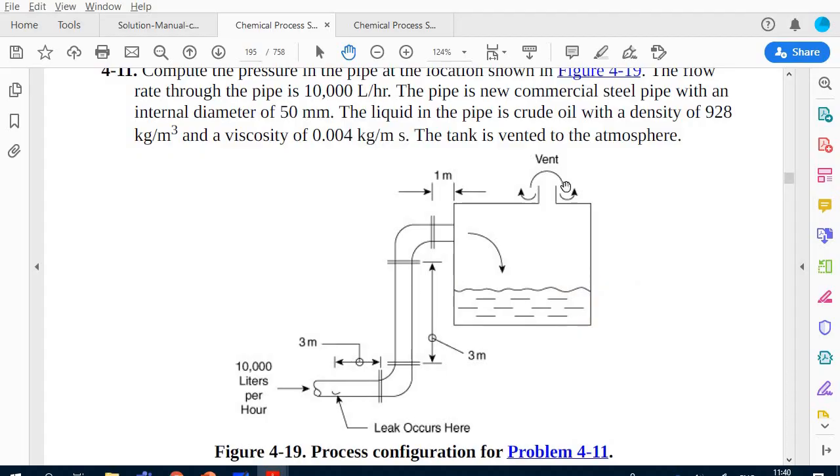Okay, and based on all that, you already can calculate the area. Well, why would I calculate the area? What information do I have here, right? I have 1000 liters per hour, so all what I need is the density. I just need the density for that. So that U is very easy to get. But I need the rest. I need the area maybe if I want the velocity, okay?